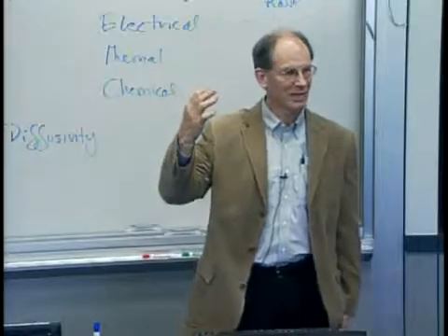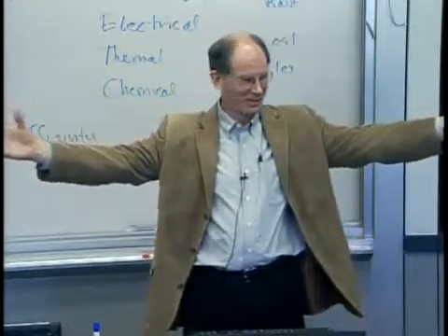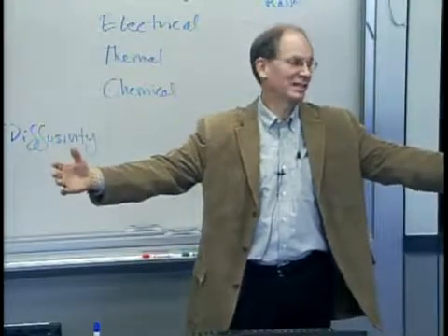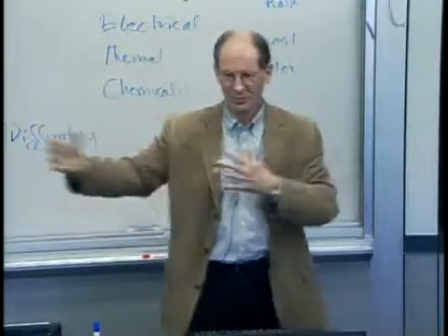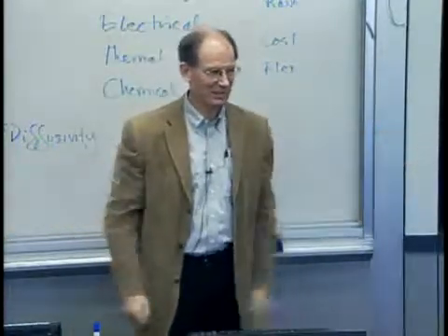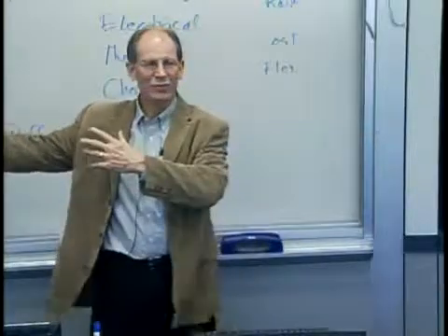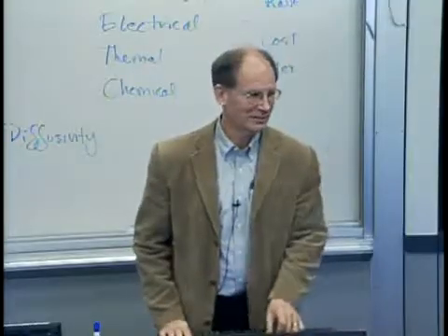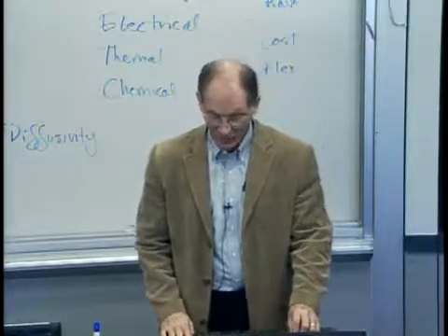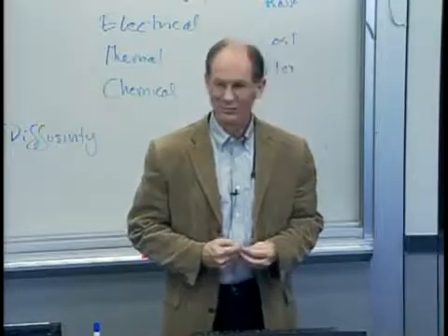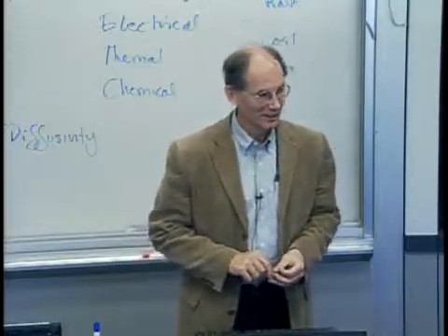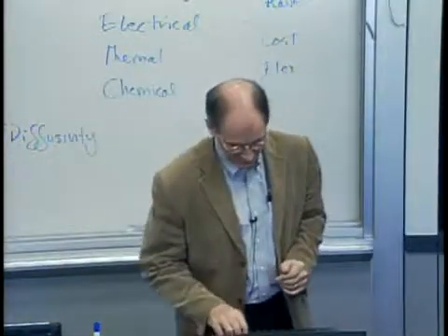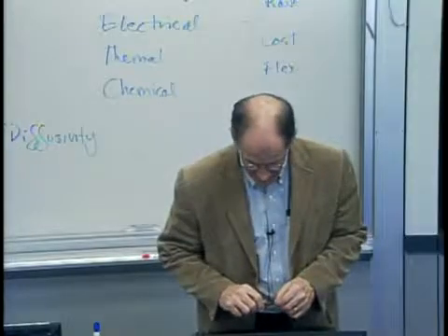How long does it take to make a side panel for a car with integral door frames and all that other stuff? Each given operation probably takes about 2 seconds. There are multiple stages, so maybe we'll give it 10 seconds by the time it's done. But blank metal goes in one end and these huge complex structures come out the other end at incredible rates. You're not going to do that with a serial process. Although I will say they've done some things with laser cutting and laser welding where that really whips along, but it's still got a ways to go, and it's much more costly. So all these things do matter, and they come in different ways.